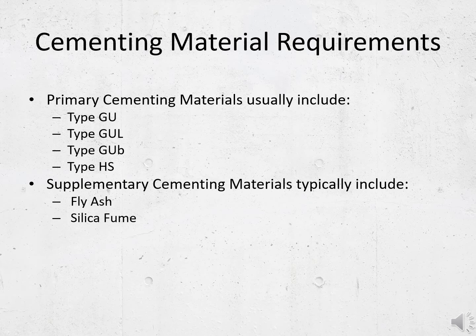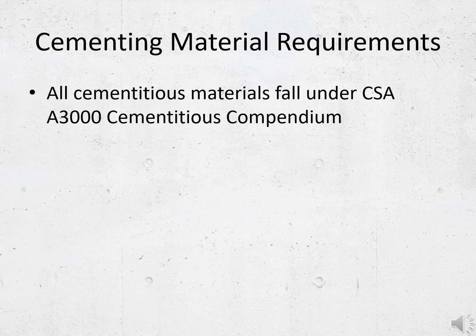With the supply from local fly ash sources becoming more disrupted of late, other sources may enter the market from nations further afield, and their compliances should be documented by a reputable firm certified to the entities previously mentioned here. Other supplementary cementing materials may be coming to the Alberta market as well and should be reviewed for compliance, as well as identification of source origin. At any rate, all cementing materials requirements can be found in the CSA A3000 Cementitious Compendium.